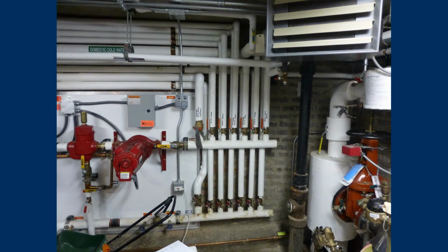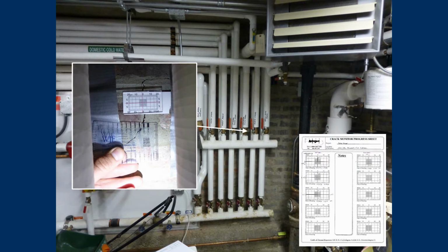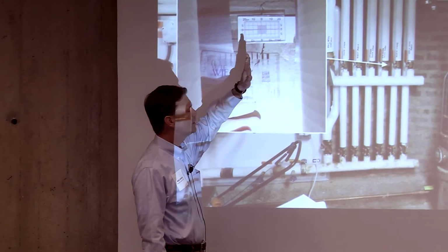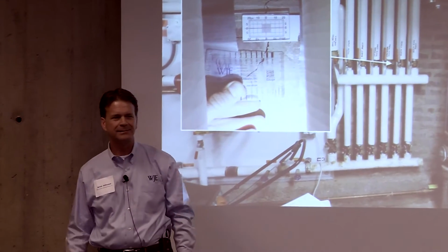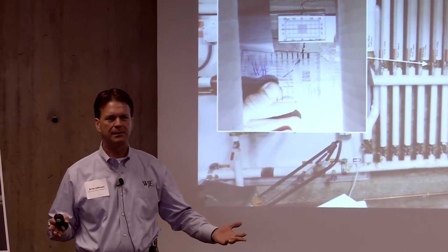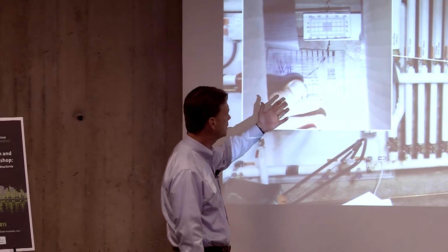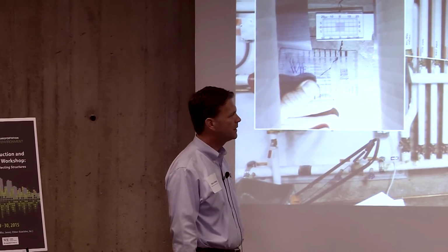At the interim survey, this was the basement inside that location, so the step crack actually kind of goes diagonally here. We didn't put any crack gauges because, well, first of all, they didn't really want us mounting gauges, but it was almost impossible to get one in. But when we saw this growth, we did go ahead and sneak in an Avongard, I love that name, Avongard crack gauge between these pipes. And so what you can see is, again, bear in mind, the crack gauge only measures the change from when you installed it to when you read it, right? It's not the total growth since the building was constructed, it's only the change. And so we monitored the change, and it was about 40 mils, which matched with our measurements on the outside.